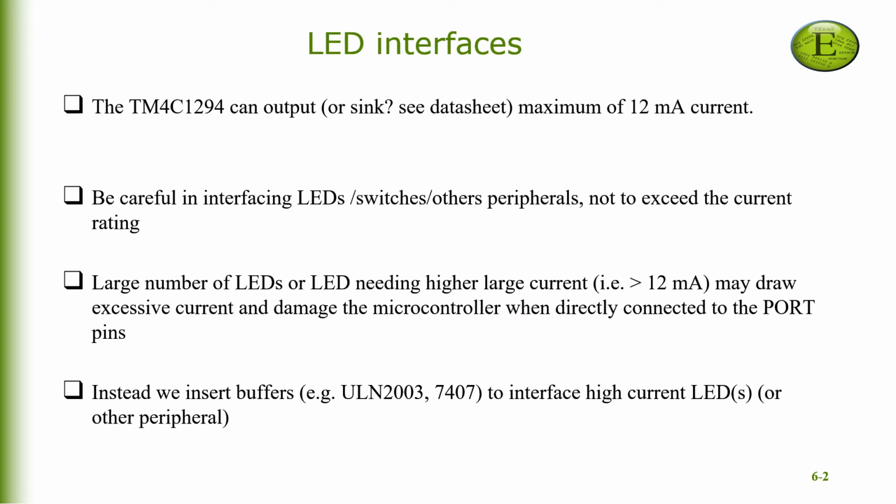In continuation of our discussion regarding the LED interfaces, there is an important precaution, which is that your microcontroller can only output a limited amount of current driving the peripherals such as LEDs, switches, and others. And there's also some limitation on the amount of current entering the microcontroller. We call it sinking the current. At this point, I don't know the exact value, but it might be helpful to consult the relevant data sheet.